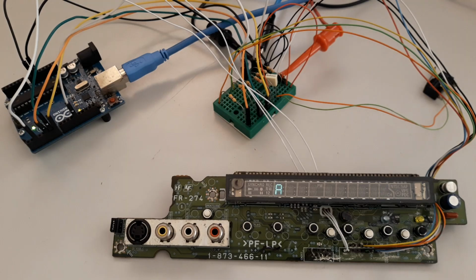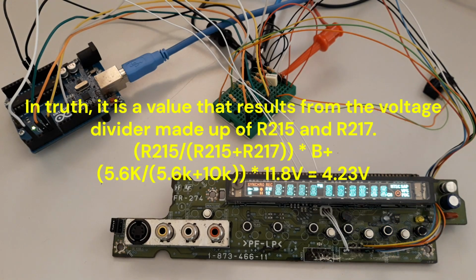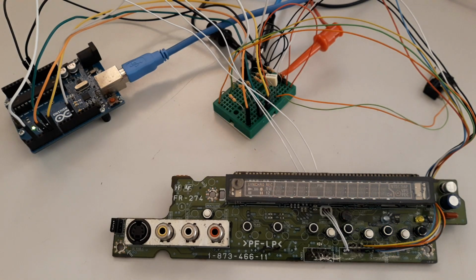Since the transistor is an NPN, it goes into saturation mode and forces the base of Q203 to a value close to 0 volts, which also leaves it in the saturation zone, since Q203 is a PNP, and provides plus 12 volts to the converter directly from the collector.